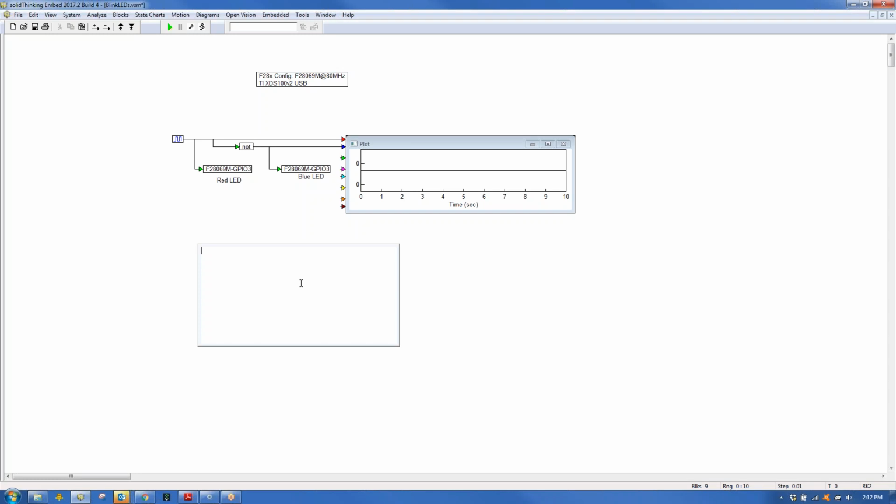Yes. So GPIO 34 is defined as the red LED, and GPIO 39 is defined as the blue LED. This is in the Texas Instrument documentation. You actually have to read it to discern this. But I'm just going to tell you that's what it is. It won't change. So if you're using these GPIO values, you will light up the red and the blue.